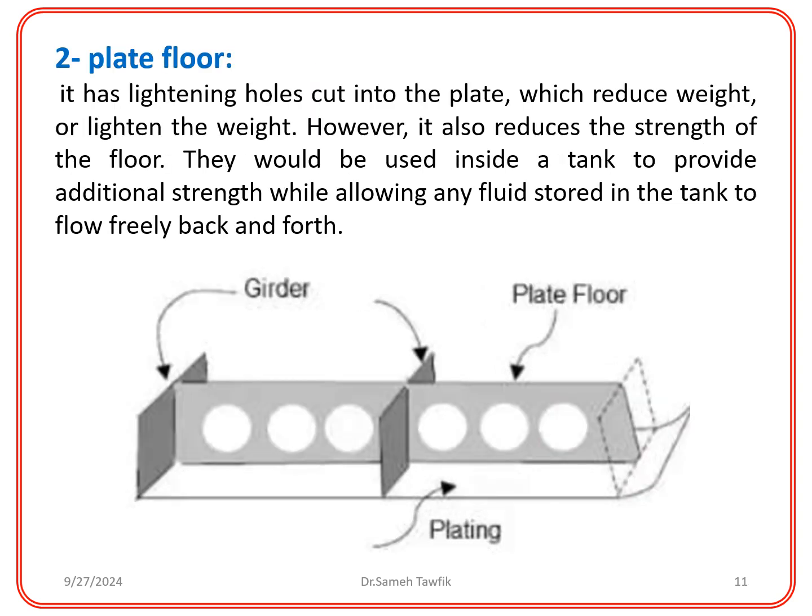Now that we've discussed solid floors, let's explore another type, plate floors with lightening holes. Unlike solid floors, plate floors have holes cut into them. These holes reduce the weight of the floor, which is beneficial for ships because lighter ships require less fuel to operate. However, cutting holes also reduces the floor's overall strength. Plates with lightening holes are often used inside tanks to provide additional support, while allowing fluids to flow freely within the tank. The holes help to reduce the weight of the floor without compromising its ability to withstand the pressure of the fluid.